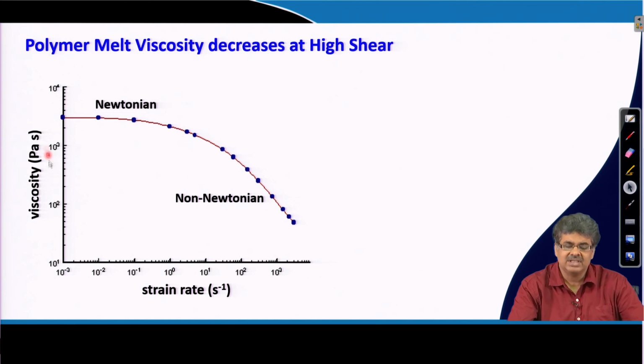But fortunately, polymers are shear thinning materials, which means that at a high strain rate, the viscosity of the polymer melt decreases a lot. So, when we are injecting the polymer melt through a die or using a screw, the shear rate or strain rate will be much higher.